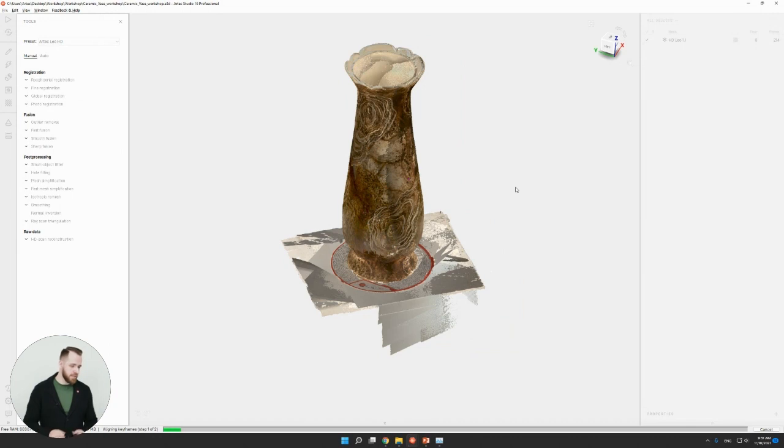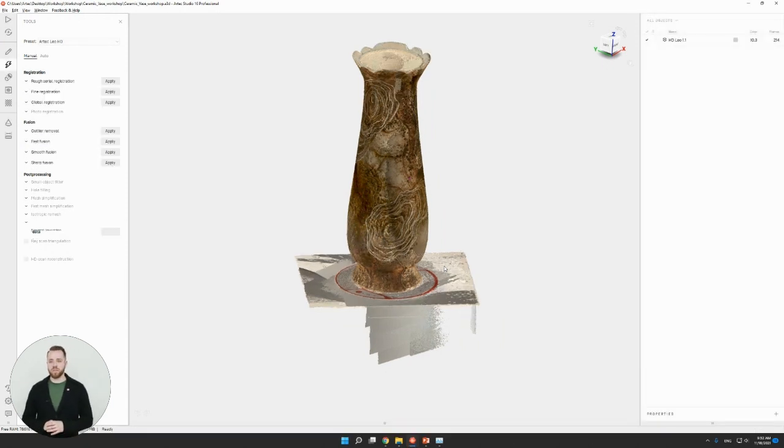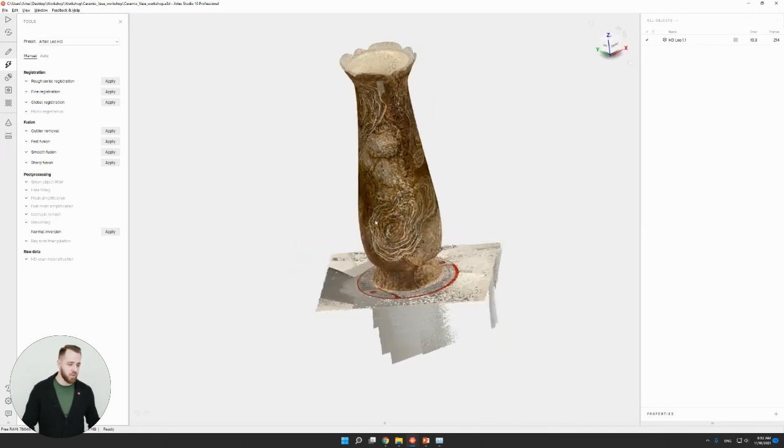Okay, it might take just a moment for the registration to complete. I use the KFR setting of 0.3, which is slightly above the default level, but it's not going to be a problem. I don't think it should take long because the computer is fairly powerful. So once I've done that, we will have all of our frames within the project perfectly aligned against each other. And I think later during processing, we'll be able to skip the global registration stage because we've already done that.